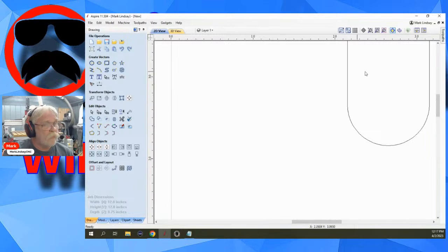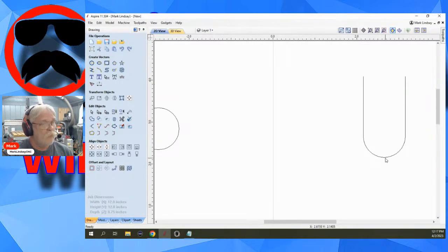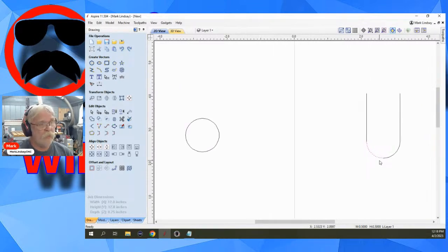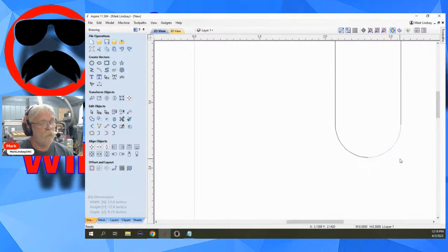It's going to carve a 1/4 inch diameter because the flutes run way up here. But this bottom radius is going to be 1/8 of an inch. So that's the difference between the diameter and the radius. The diameter from here to here may be 1/4 of an inch, but the radius from here around this way is 1/8 of an inch. So I hope that kind of clears that up. And I hope that was what you were asking.